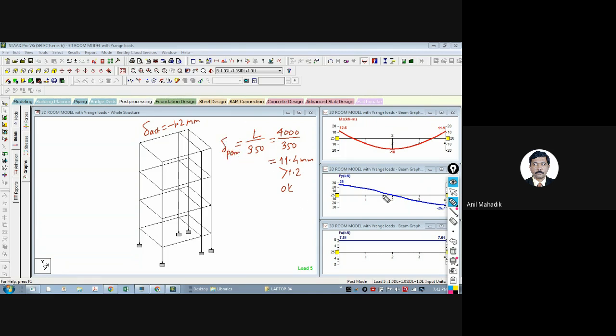All of you know that in any design, there are only two criteria, strength and serviceability. That is the design, nothing but. Serviceability means deflection, let's say. So we design for strength and we check the deflections for service load combination. That's it. That is the design.